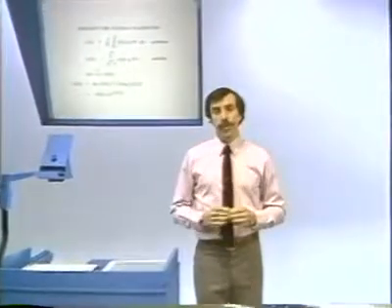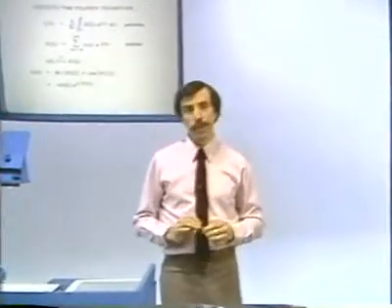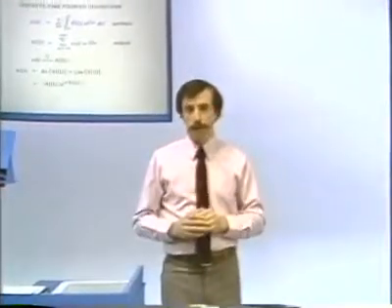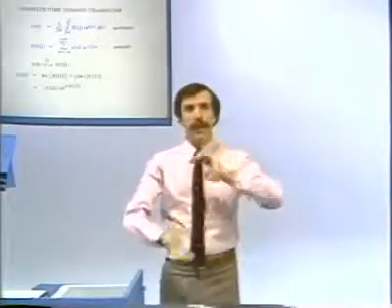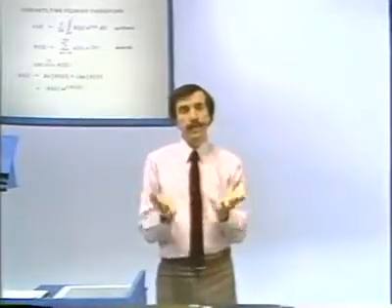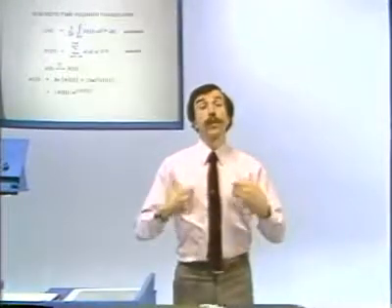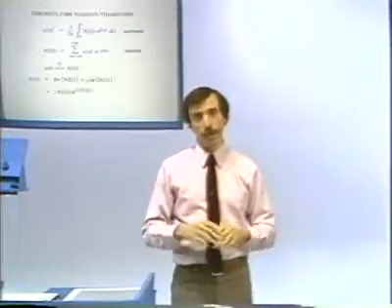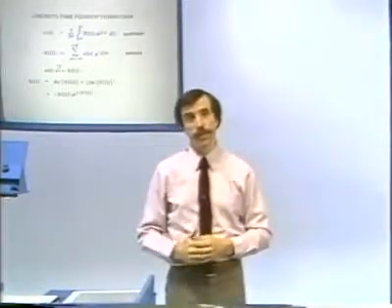There are a number of things to focus on as you look at this, and we'll talk about some of its properties actually in the next lecture, but some of the points that I'd like you to think about and focus on is the fact that now there is somewhat of an imbalance or lack of duality between the time domain and frequency domain. X of n, which is our aperiodic signal, is, of course, discrete. Its Fourier transform, x of omega, is a function of a continuous variable. Omega is a continuous variable. That is essentially what represents the envelope.